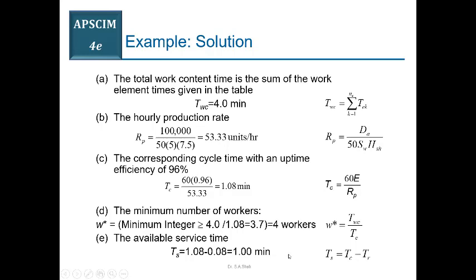So जो लाइन बैलेंसिंग फार्मूलेशन आप करेंगे, it will be based on this figure, on 1 minute, not on 1.08 minute. You remember this one. So theoretically, number of workers or number of workstation is 4, and then now you will find for the actual scenario जब आप लोड डिस्ट्रीब्यूशन करेंगे तो क्या आपके पास आ सकता है.